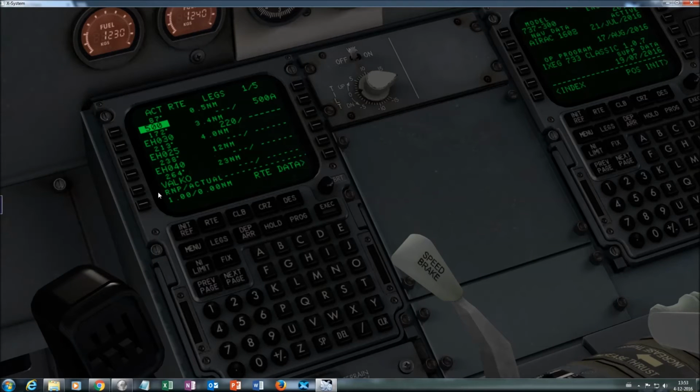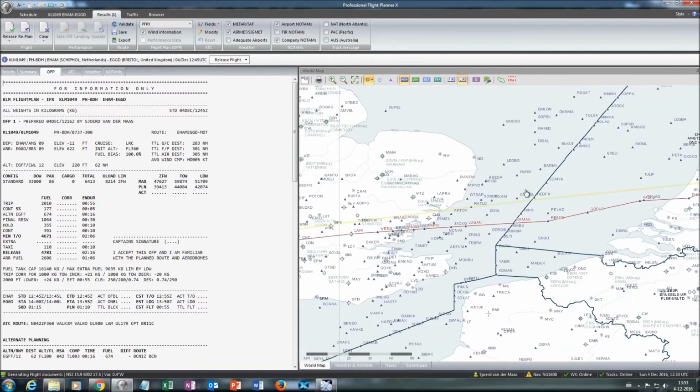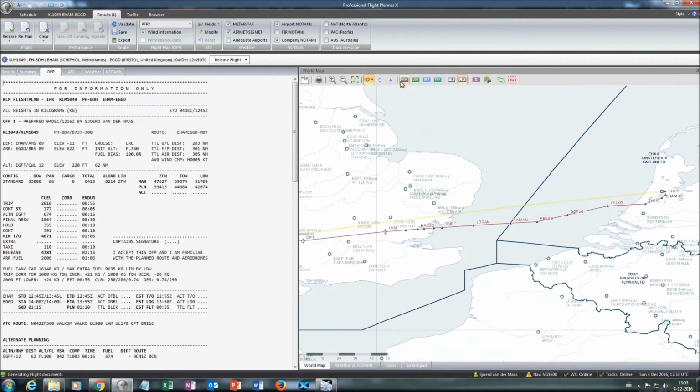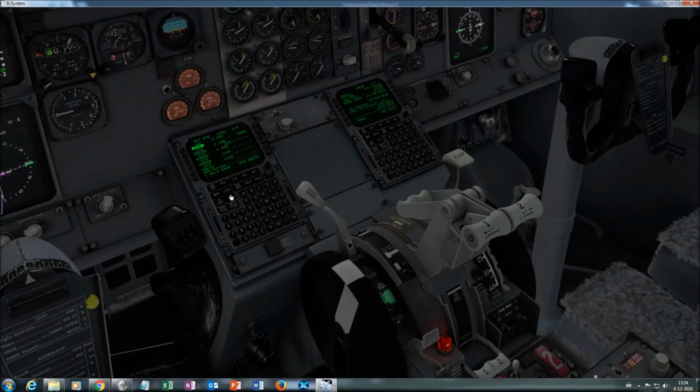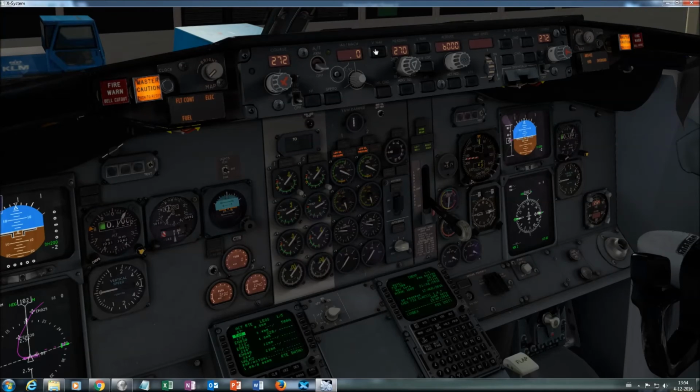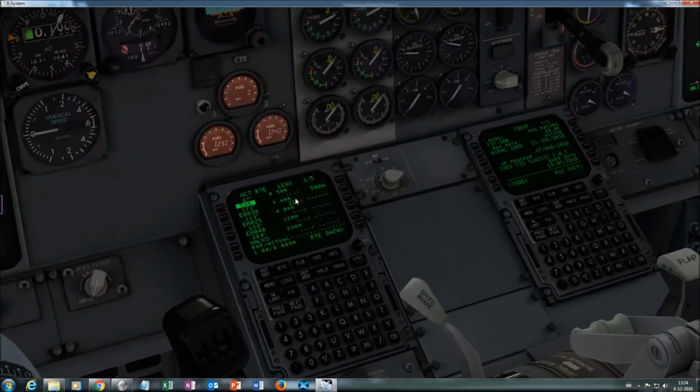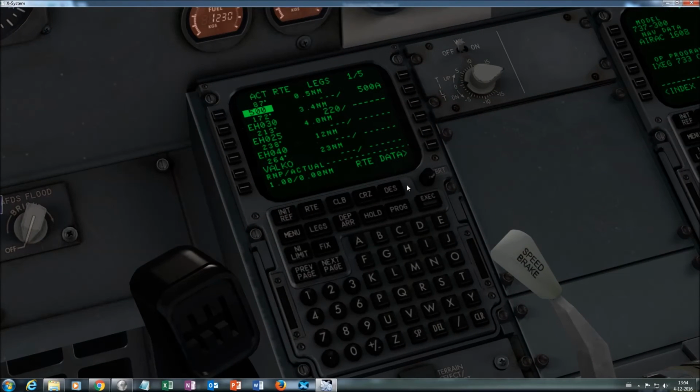This entire process of getting from A to B is what we call lateral navigation. It's the navigation over the surface of the Earth, or as you might know, LNAV. But there's another button that says VNAV, vertical navigation. And vertical navigation has everything to do with the performance of the aircraft. And that's not yet calculated because for the performance of the aircraft, we need details about weight and balance and about weather en route and stuff like that.